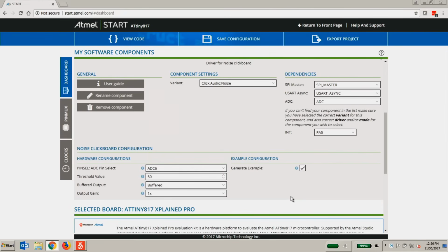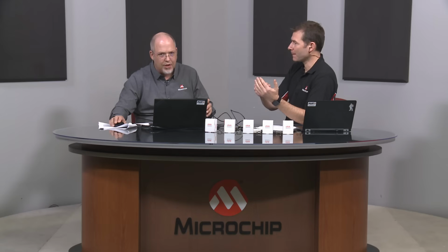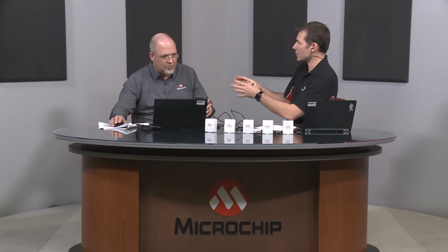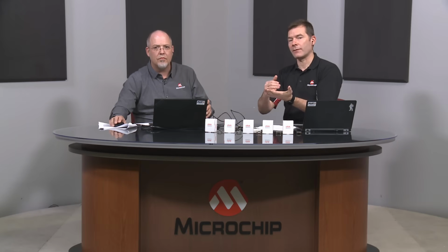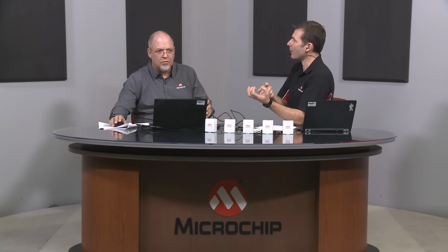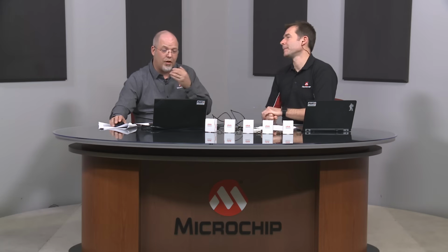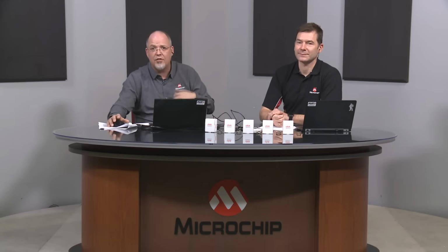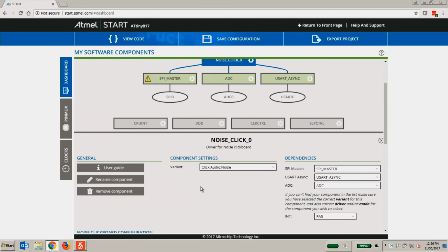So if we just repeat what the module actually does, it is measuring the signal from a microphone. It is then comparing that signal to your reference level. So we just keep it simple here. That is what you just set up, the reference level. If it's passing that level, it would generate an interrupt. But you'd also be able to read the microphone power level with the ADC, and that's why you have the ADC there as well. There's a lot going on in this little circuit, but it's been put together for you so you don't have to do the bench testing with it, and the schematics are available. It's kind of an open source thing.